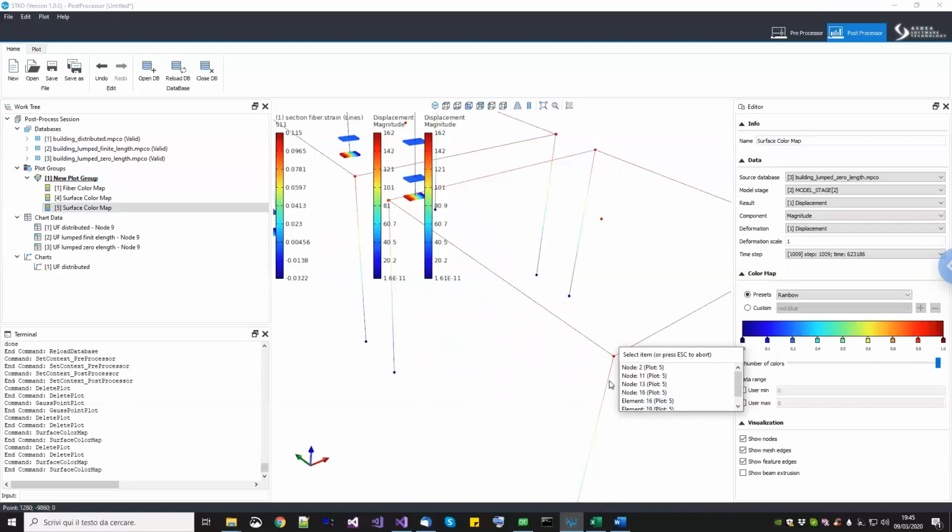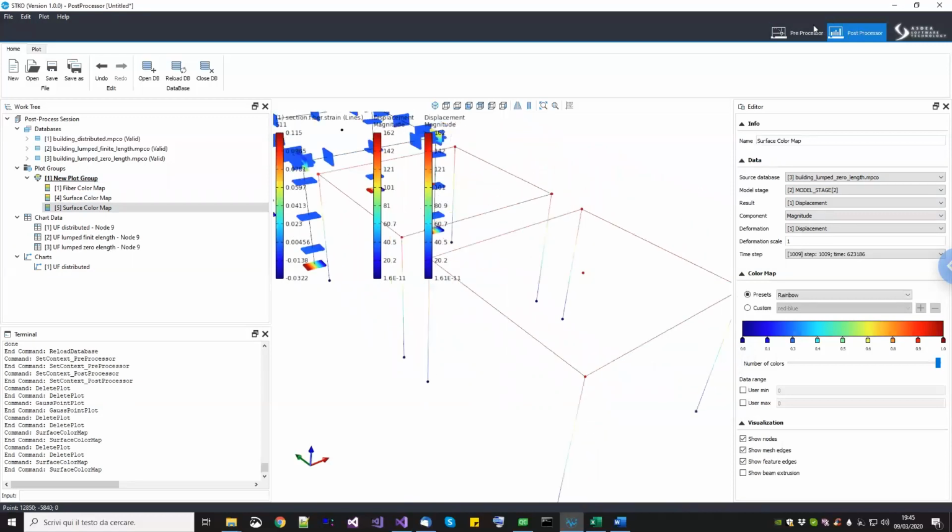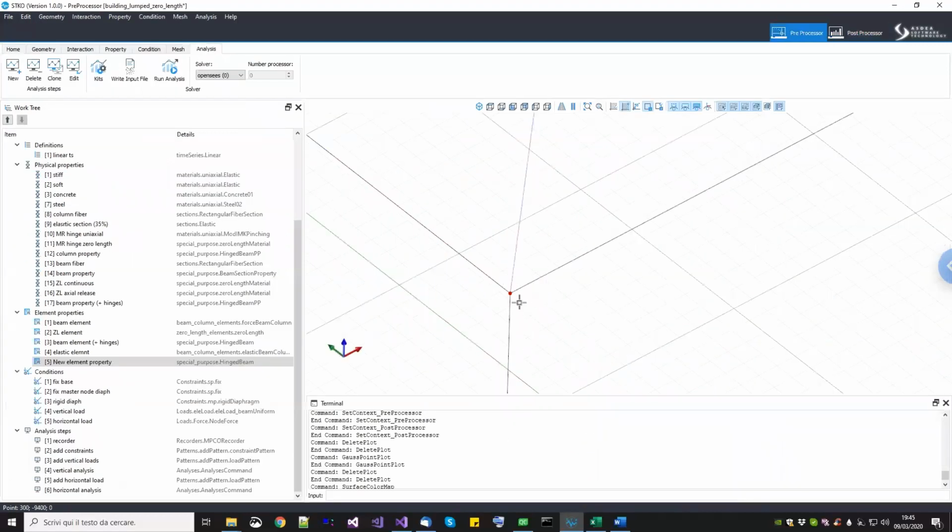Now in this case, also the column has a release with respect to the corner nodes. And in fact, I see four coinciding nodes. So this is basically the difference. While in STKO you draw everything connected, the OpenSees model automatically has these nodes disconnected and joined with a zero length element.